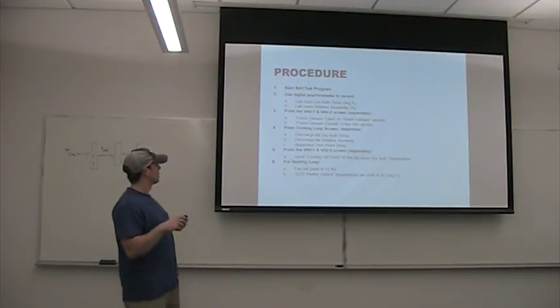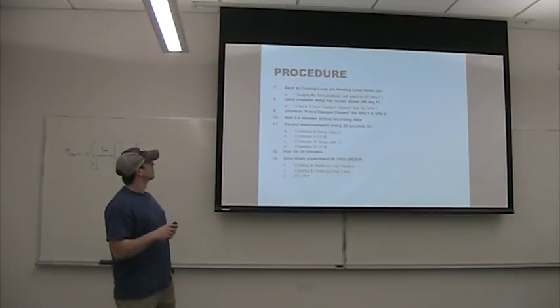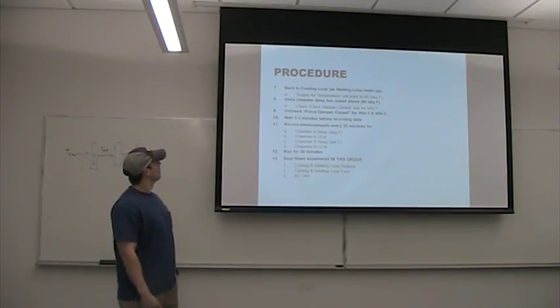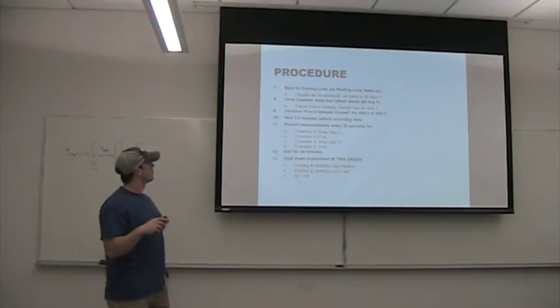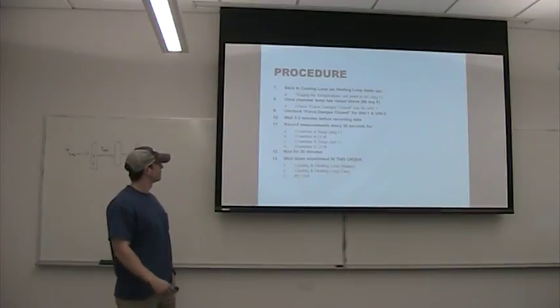So in the cooling loop, you're then going to do something with your discharge air temperature. Pretty much this is just setting up all your stuff. It's pretty detailed, but we can follow along in the handouts. Back to the cooling loop. You want to make sure you wait 2 to 3 minutes before recording all the data that you just set up in that really detailed section.